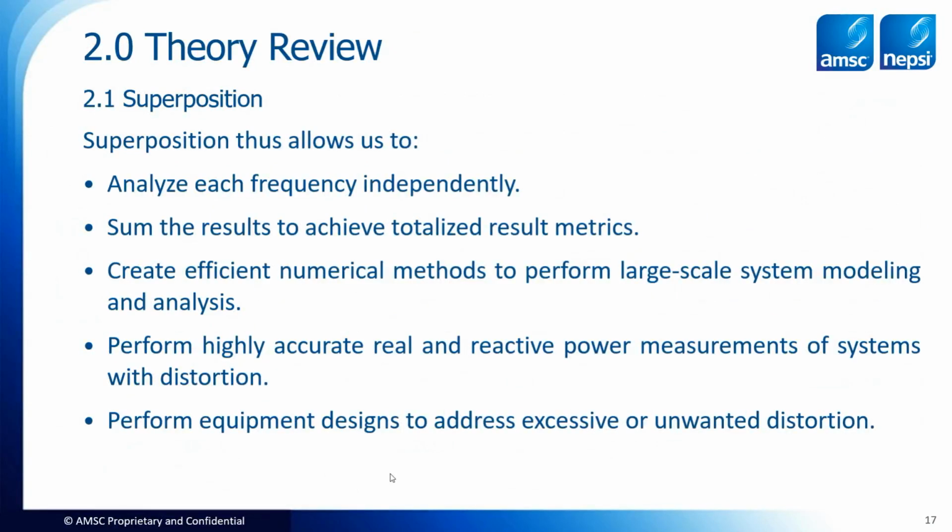So, superposition thus allows us to analyze each frequency independently, sum the results to achieve totalized result metrics, like total harmonic distortion, and a number of these other values that we look at in harmonics. It allows us to create efficient numerical methods to perform the type of analyses that we want to do, especially on large-scale systems. And it allows us to perform highly accurate real and reactive power measurements, and finally, to perform equipment designs to address excessive or unwanted distortion.